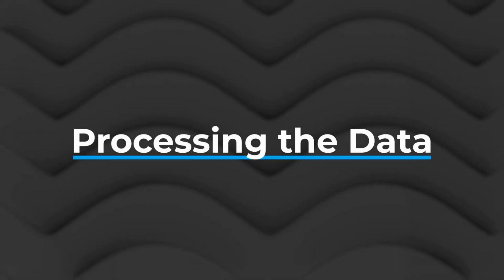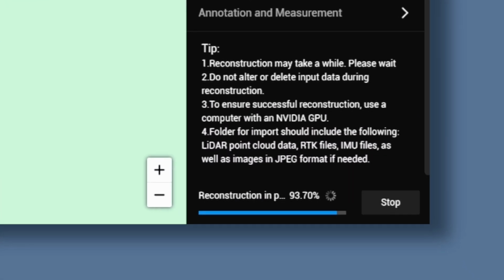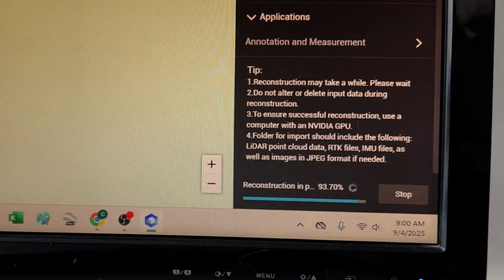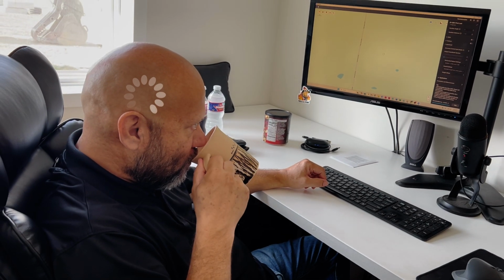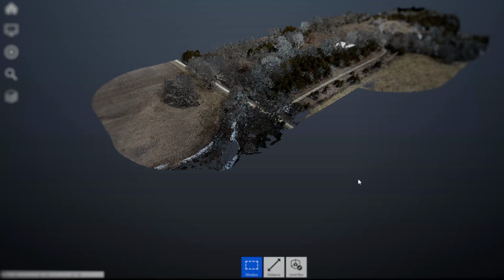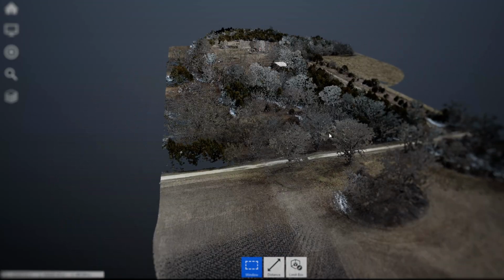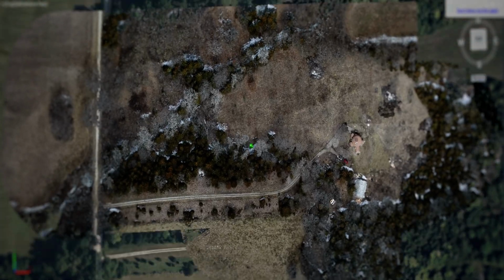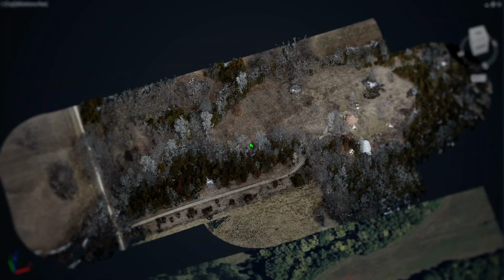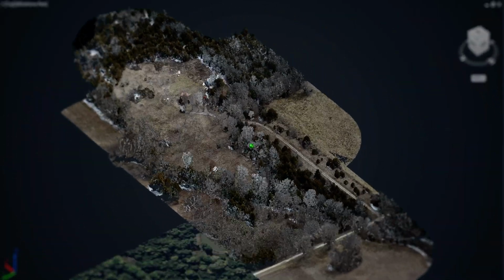Once we have the LiDAR data, the very first thing is processing that into an actual format that our AutoCAD software is able to read. There's a software we're able to use immediately to essentially take that survey, and the LiDAR pretty much creates a point cloud, so every single survey point is assigned a color. And it's assigned an elevation and a geolocation, so it maps out and creates a perfect 3D model of exactly what that property looks like.